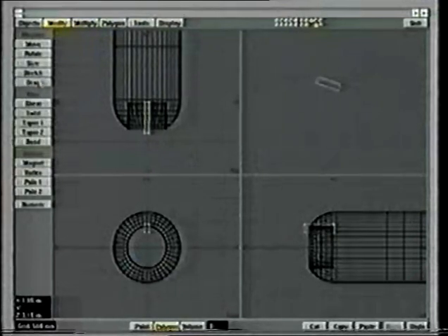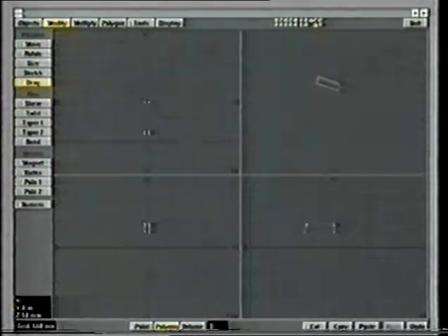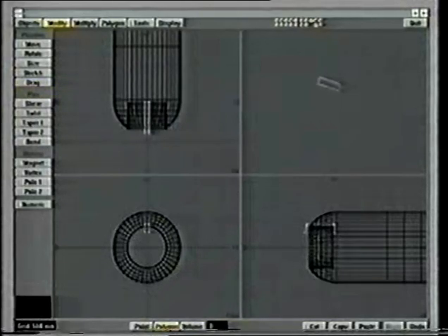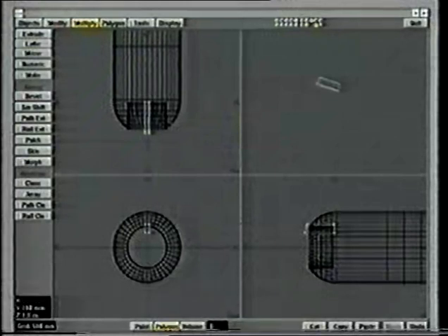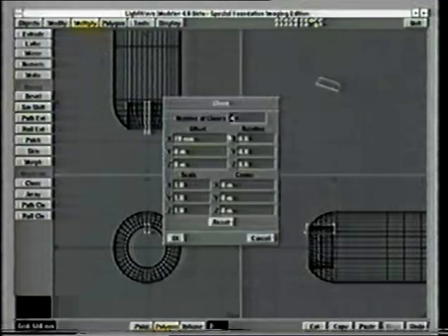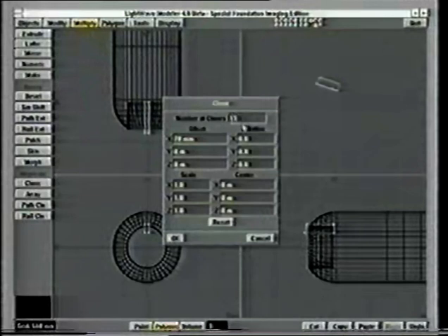Now let's do a drag to get the sort of shape I'm looking for. Looks pretty good. And I'm going to do the same on the inside here, keeping those same values. Alright, now I have one of the pieces of radial detail that I'm going to use. So, how many times do I want to put this around? Probably as many as 12. So, let's do a multiply clone. I want 12 total, so I don't make the mistake of putting 12 in here and put 11. Because otherwise you'll duplicate the object right over the original object.